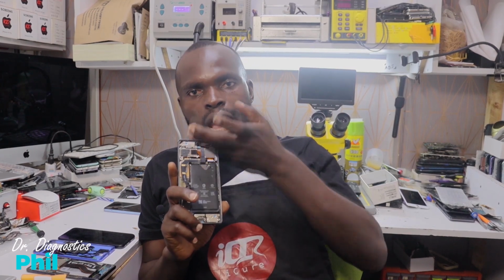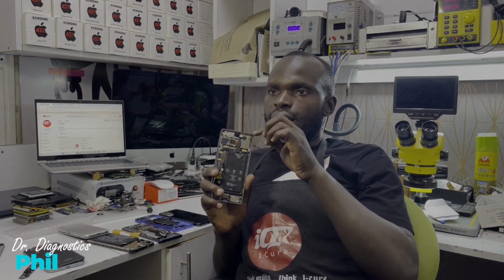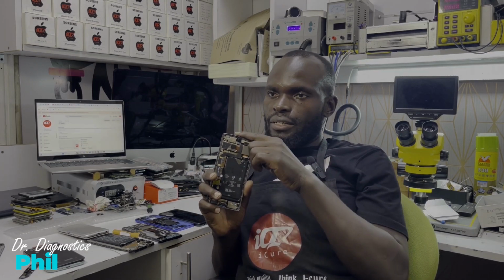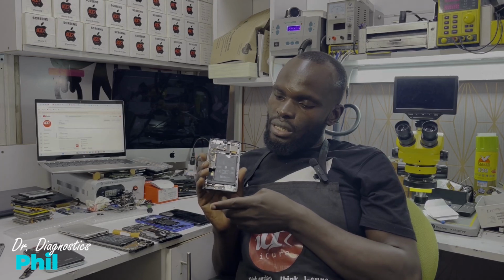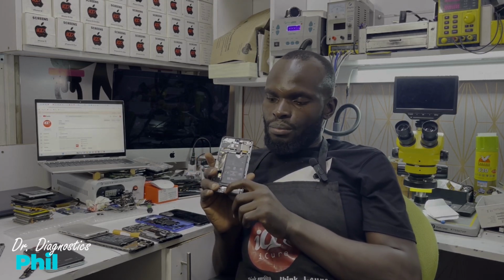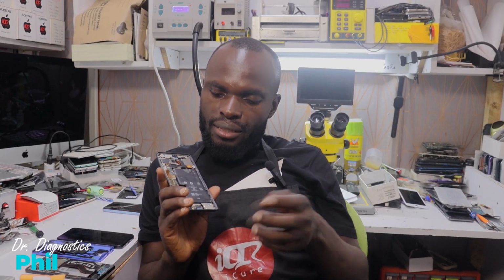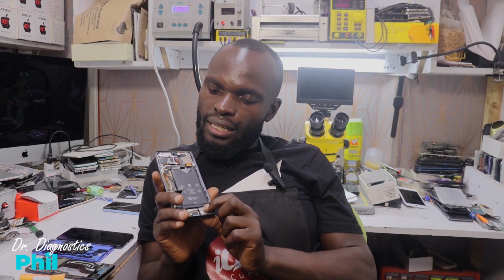The earpiece is located at the uppermost part of the phone, so that in the normal way of handling a phone, you can hear because the earpiece is located close to the ear, to where you can put your phone to the ears. The earpiece is located at the upper section. Remember, the earpiece is located at the upper section. The mouthpiece is located at the lower section. So you just have to identify how a mouthpiece looks like, different kinds of mouthpiece, so that it can be easier for you to fix or replace. The ringer, I've said, is located at the lower chamber.